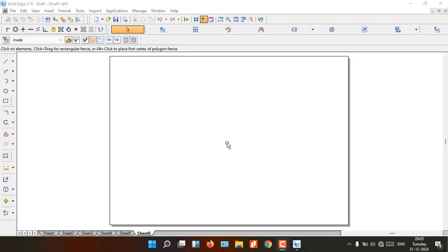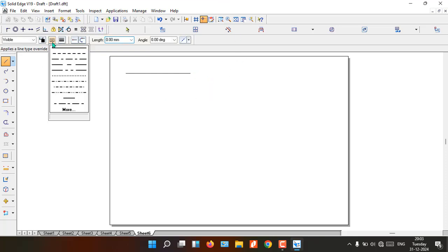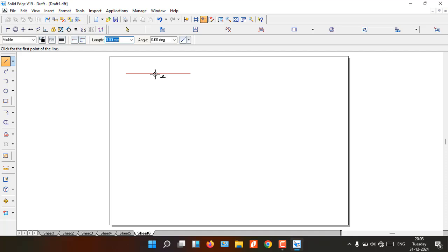Hello students, here we have a development of a funnel. The funnel will have a frustum of a cone followed by a cylinder. So first of all, we need to have the 2D sketch of the funnel, which says the top surface has a diameter of 80, and take a midpoint of that. From the midpoint, the height they have given is 60.